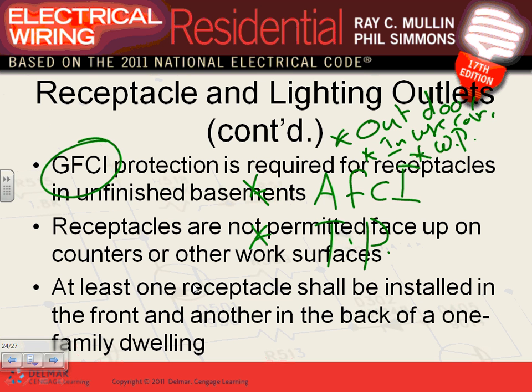If the apartment unit in an apartment building has an individual door that opens directly to the outdoor, which your project has two of them, so basically they have two entrances to the apartment. They can get from the common space stairway in, or they have a door that opens to the outside directly. If you have a door that opens to the outside directly, then you need a receptacle. For the apartments that we have, I'm asking you to put two in the front and two in the back, convenient. And you're going to add also one, powered from the common spaces, for holidays and so forth. Good design, no code.